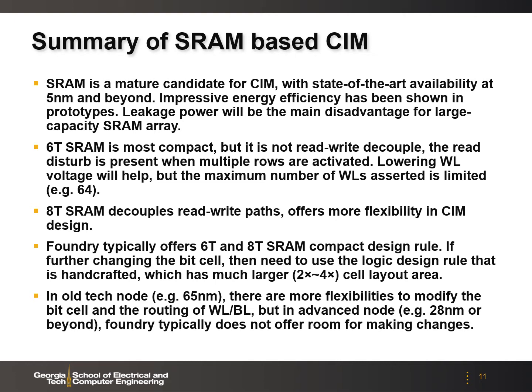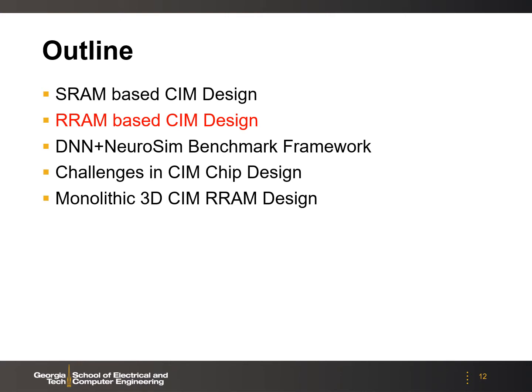In the older technology nodes, for example 65 nanometer, there is much room to modify the bit cell and reroute the interconnects. But in advanced nodes, for example 28 nanometer or beyond, foundries typically will not allow changes to the bit cells. Okay, now let's move on to the RRAM-based design.